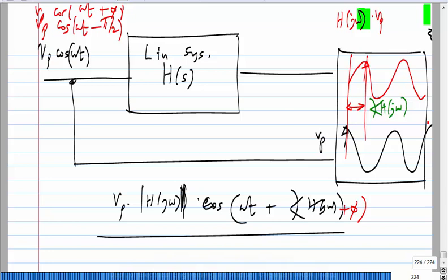So the transfer function itself is a complex number. What is that telling you? That is telling you how a complex exponential gets multiplied when it goes through a linear system. And why complex exponential? We use it from a practical viewpoint: calculating the response to cos omega t is a lot more complicated than doing it for exponential j omega t, and from exponential j omega t, I can very easily get the response to cos omega t. So that's why I do this. This is the analysis viewpoint, right? And finally, you don't even have to go through the intermediate steps of, oh, I have an input of exponential j omega t, this is what this gives me, I take the real part of that and so on.